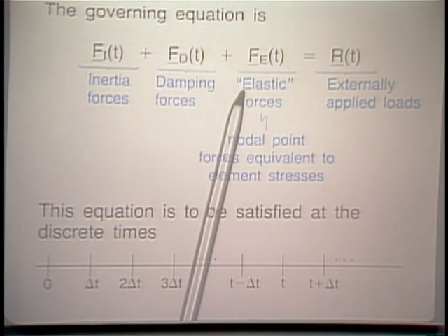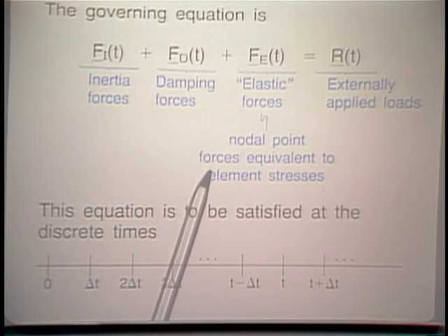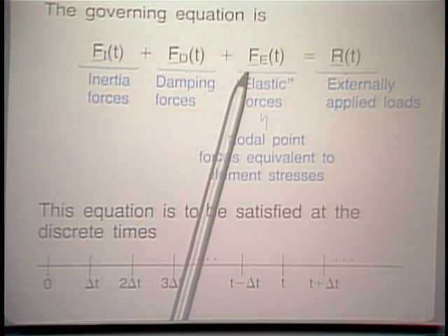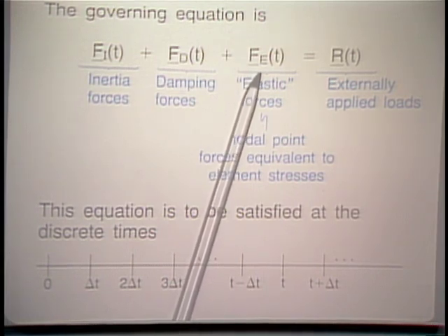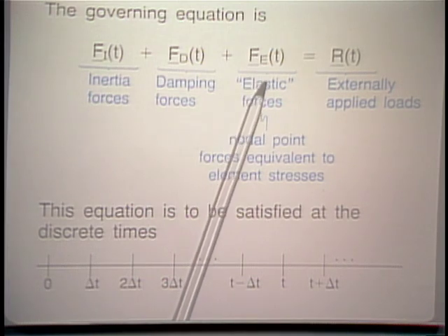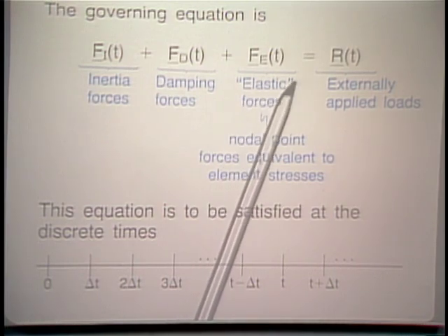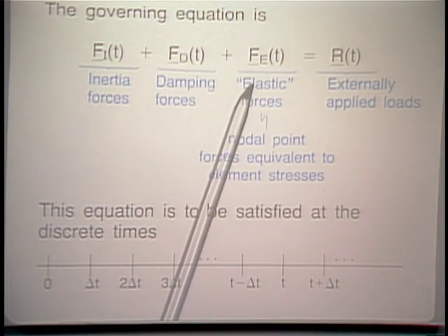The elastic forces, here elastic in quotes, are actually the nodal point forces that are equivalent to the internal element stresses, and we talked in the earlier lectures about how we evaluate them, using, in the updated Lagrangian formulation, Cauchy stresses, in the total Lagrangian formulation, the second Piola-Kirchhoff stresses, etc. Please look up all the information that we talked about in the earlier lectures if you want to study how we calculate these forces in large displacement, large deformation, large strain analysis.